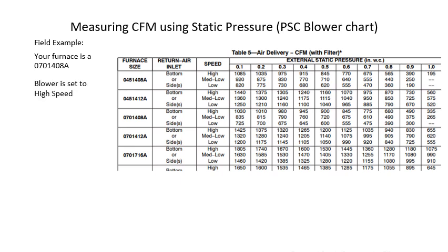Our blower speed currently is set to high speed. So out of that entire chart, again, we've just narrowed it down to the one model of furnace and the one fan speed of high. So we've narrowed this down to one row on this entire chart. And again, we've measured our external static pressure at 0.5. So what is our CFM? It's 900 CFM. So very similar ways of measuring CFMs using the external static pressure.